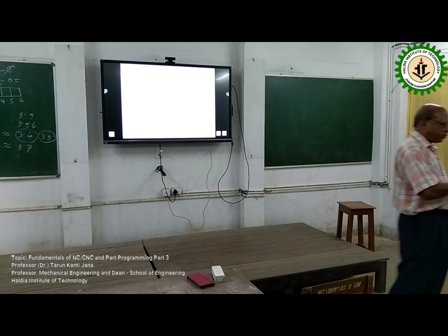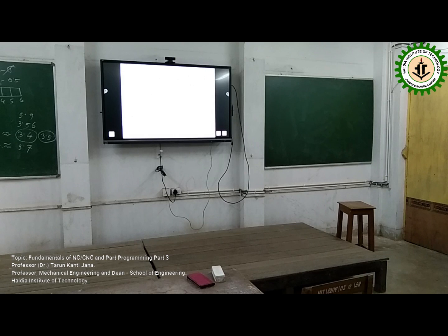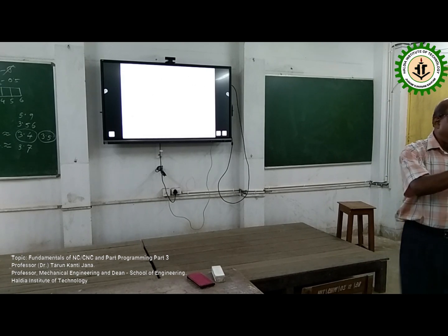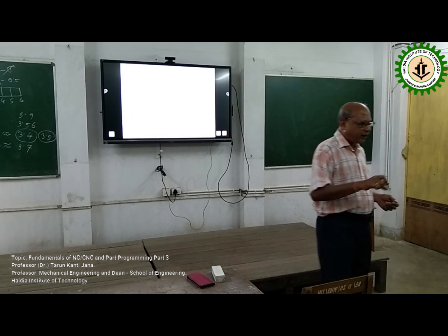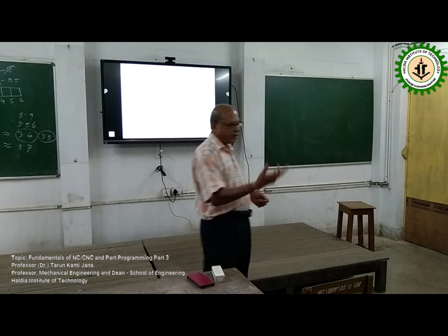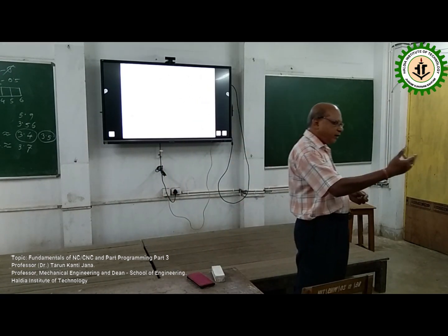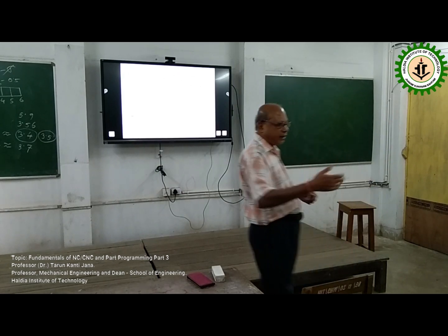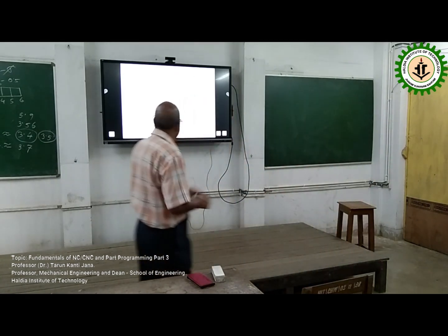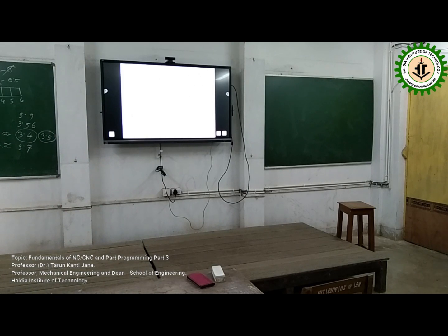In our steam table also we interpolate. Some steam-related properties are available at 1 bar, 2 bar, 3 bar. If you are interested in calculating the steam property at 1.7 bar, it is not available. Then we take the 1 bar data and 2 bar data, and we interpolate.